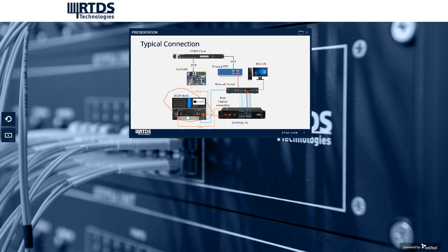In the other direction, the external IED can also publish SV to the network, and the GTFPGA-SV can subscribe to the SV, and then feed all the information back to the RTDS simulator here. So this is a fully two-way communication. Of course, all the devices in this setup are synchronized to the same clock, using PTP, so that all the devices have the same time reference.